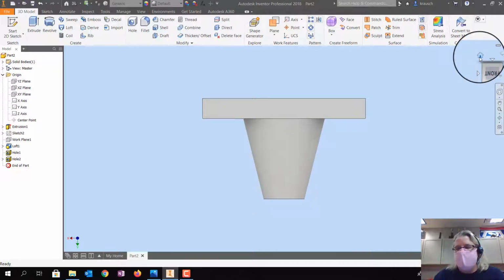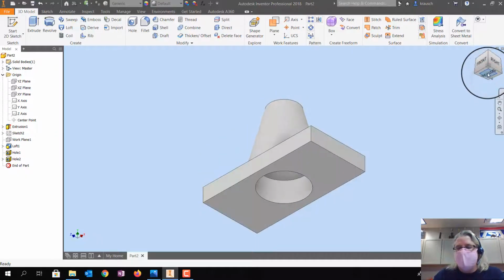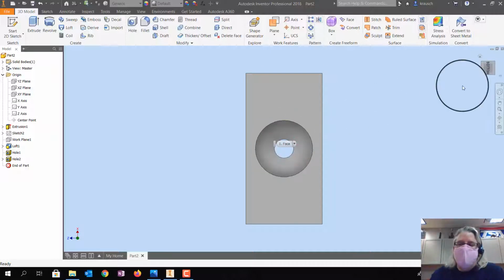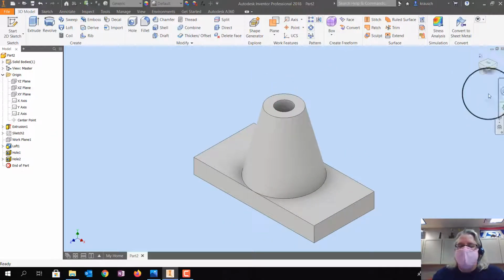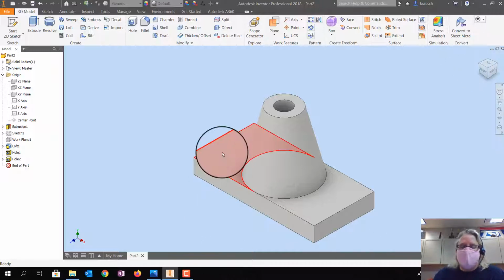Guess what? That's called a counterbore. And we're going to draw some more counterbores here. A counterbore is a circle with a smaller diameter seated inside of a circle with a larger diameter. The big circle kind of sits on top of it like a hat. And the reason you would draw those and use those is if you were making something like a picnic table and you wanted to hide the top of the bolt so it didn't sit on top of the work, meaning the wood or the metal, you could recess the bolt just a bit. Okay, so let's draw the other 4.